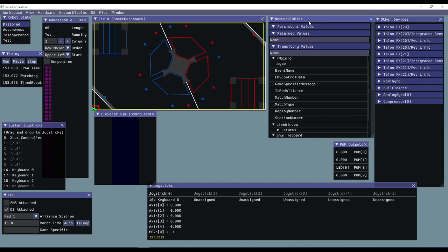And in addition to that, we can do even more stuff. So we have it set up in the code right now, and we'll go through some of how that works, where it's going to actually simulate the motion. So even though the Romy's not connected at all right now, as it tells the Romy to move in simulation, it's getting enough feedback to simulated encoders to tell the simulator how far the motors have moved, and we can actually plot that out on this screen.